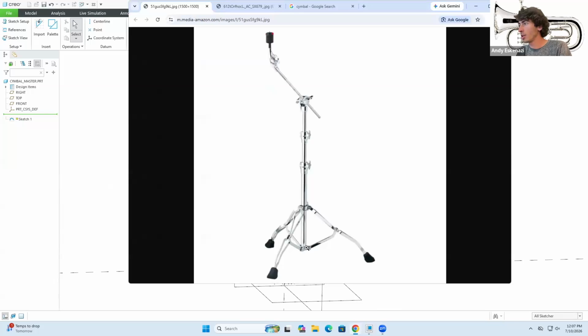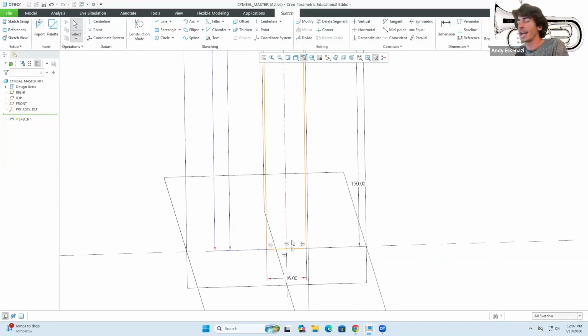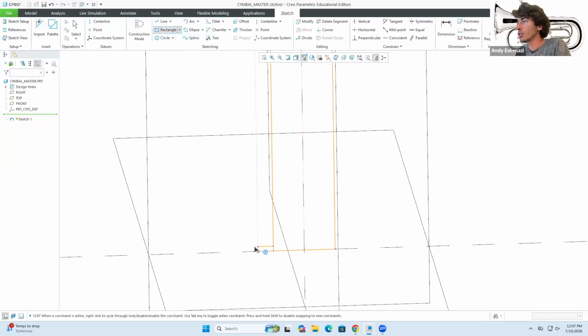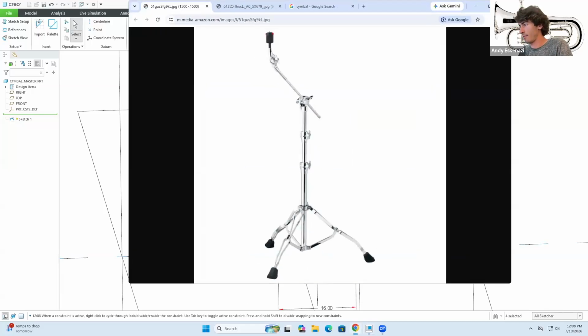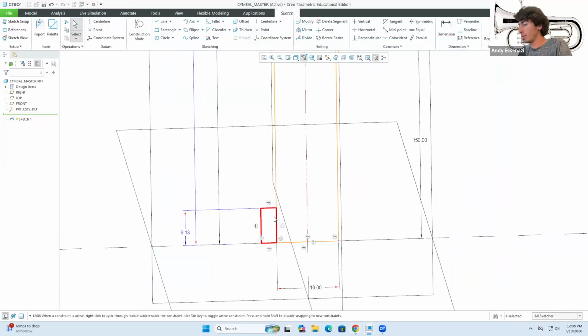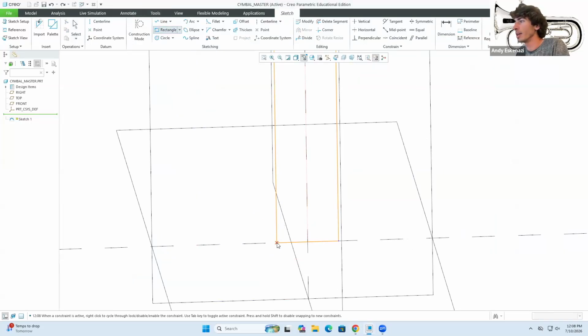Now, if we go back here, you'll see that there's another attachment piece that comes. You may remember this from the in-person video when we did the music stand, where there's like a tripod of sorts and a freeway hinge. We can cut that in here by, remember that we are going to revolve this. So this is as if I was just looking at a section of this part. I can draw a little ring that comes like that. I think 2 millimeters. I might make it thinner.